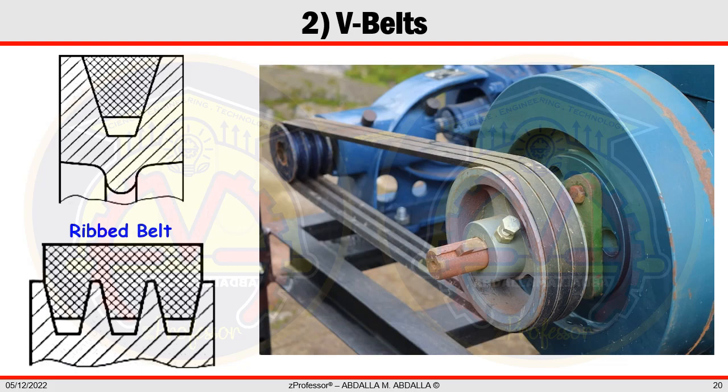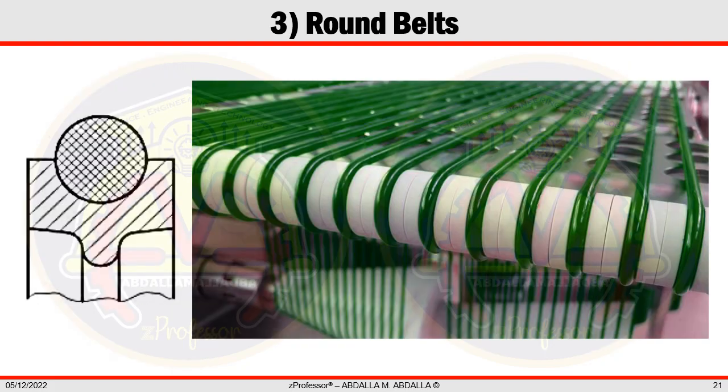with a V-belt. While the V-belt segment secures the sheave, the flat belt section carries weight. Belts with ribs increase their ability to bear a load and reduce excessive bending strain. Round belts, which have a circular cross-section and are only suitable for light operations, are mostly utilized in household appliances and machines for the textile industry. They may be bought in a variety of lengths or can be customized for your needs. They can be attached with a staple, a metallic connection, glue, or welding.